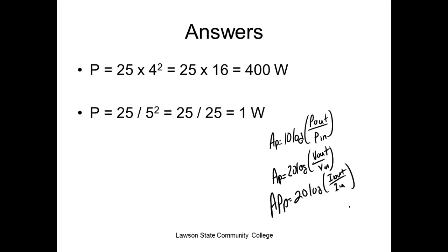It's squared. That's right. That's what it is. It's dB. So to go to dB on power, we multiply by 10, but if it's voltage, I multiply by 20, and you get exactly the same power. You calculate power gain, but how do you calculate it? You're calculating it by voltage, right? Y'all understand that? Yes or no? So here's our formula for dB.